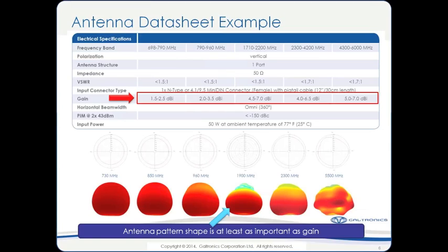And then finally at the bottom of the page is the shape of the antenna pattern. This is, in my opinion, the single most important aspect of choosing an antenna. The antenna's job is to provide power where you want to provide capacity. So if you're designing a broadcast system like in-building DAS or in-building small cells, you want to not have a preference for any particular direction.